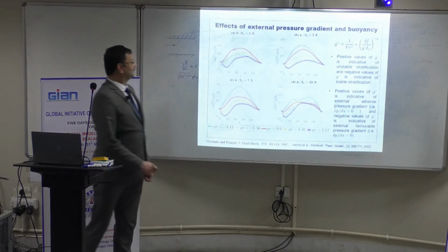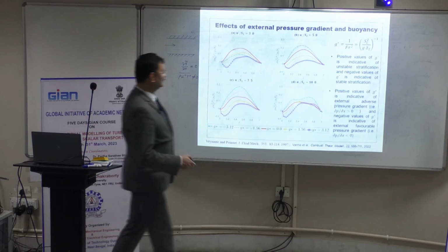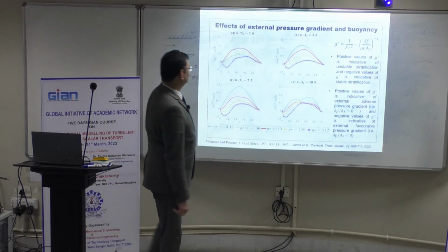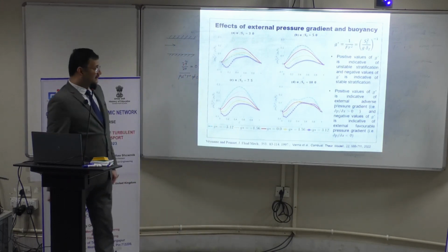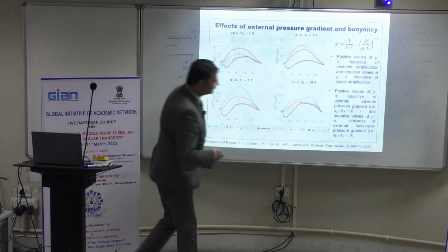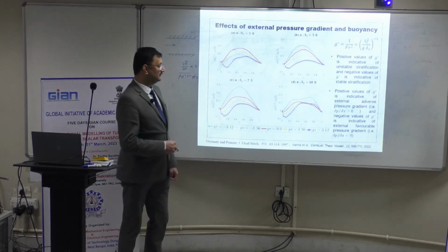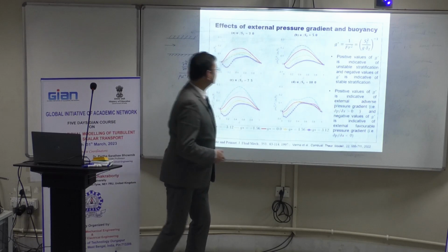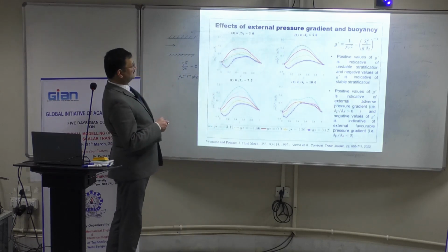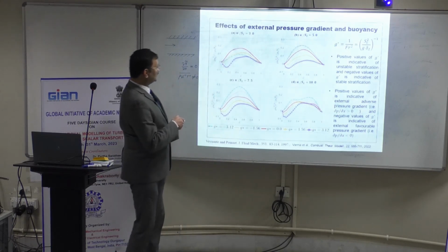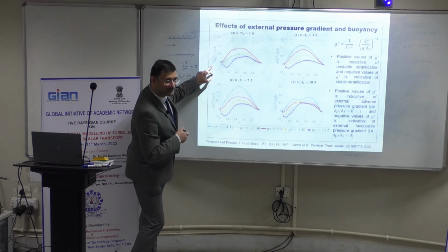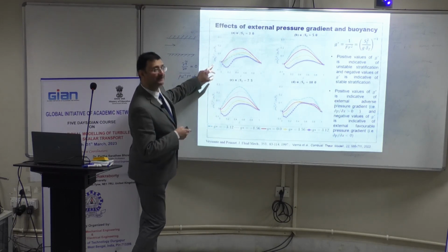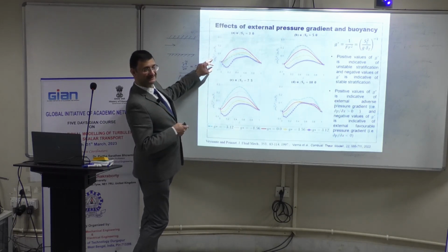What really happens for different values of G star? You will see the turbulence effects are going to be magnified for increasing G star. So you will see for this one, you start to see gradient type of transport towards the leading edge of the flame, where the thermal expansion effects are not strong.